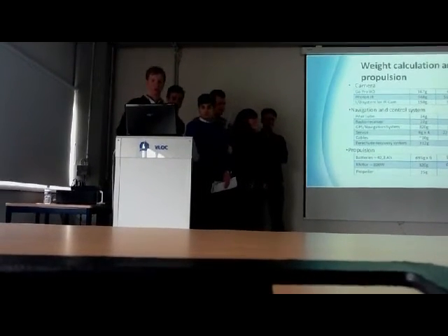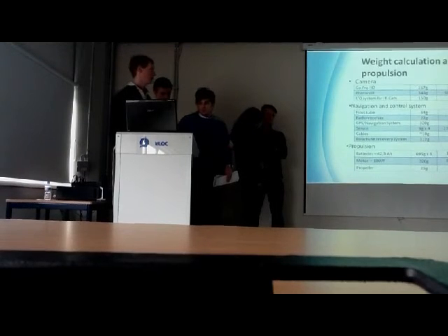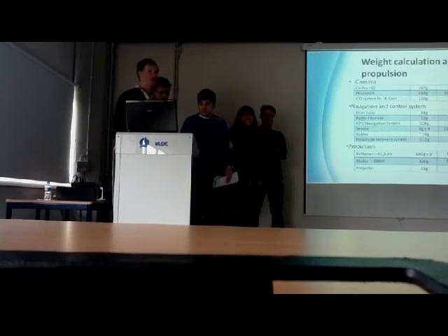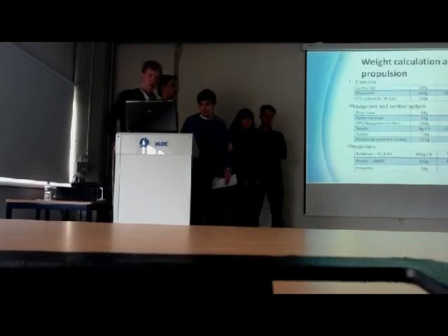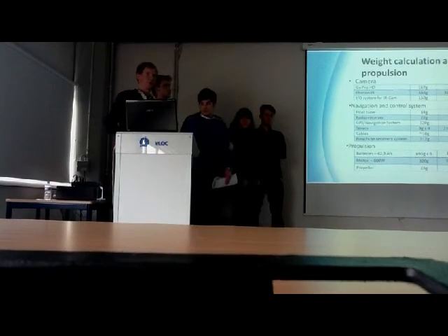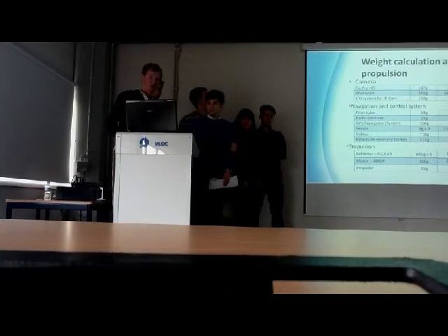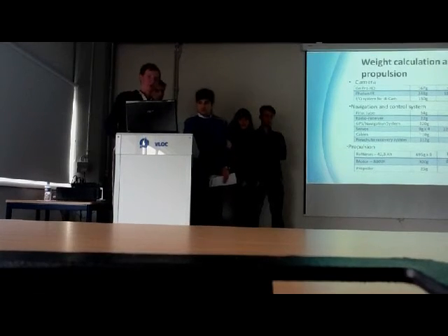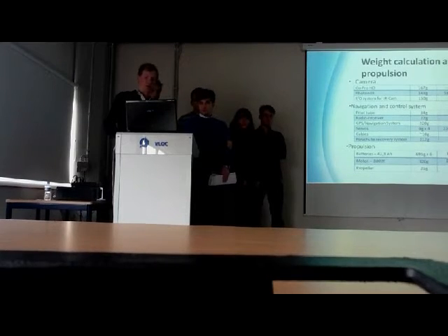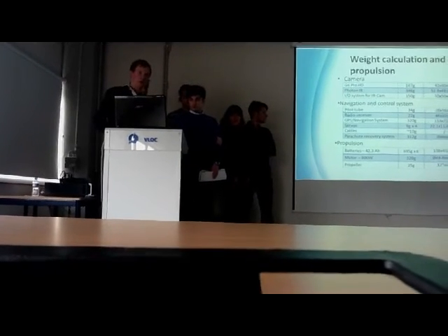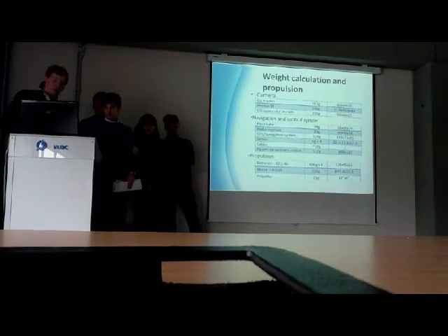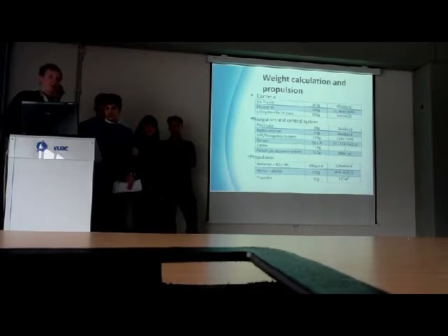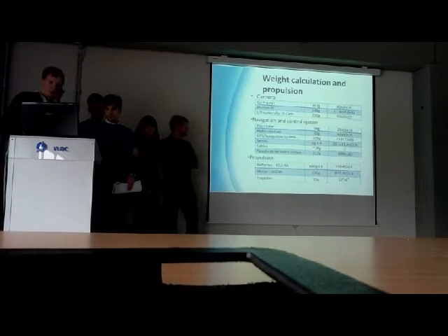So we chose the GoPro HD digital camera because of its high resolution and relatively low weight, and it is quite strong. In case we have to do some night missions, we also chose an infrared camera, the Photon IR, which is also used for different other UAVs, and it is really small. We needed an input-output system for the IR cam. It wasn't integrated, so we added it.